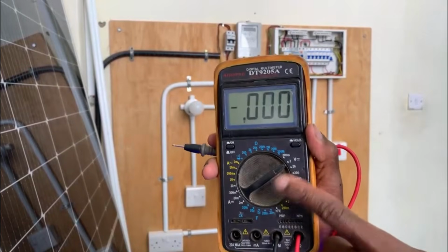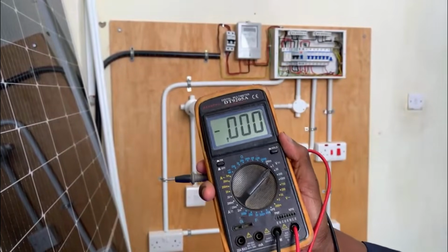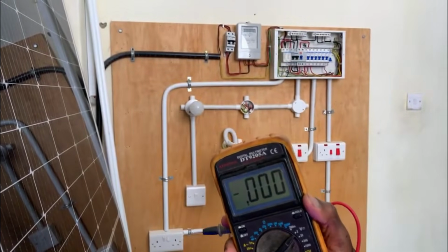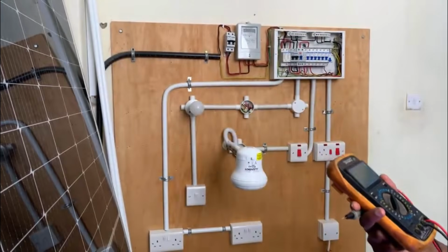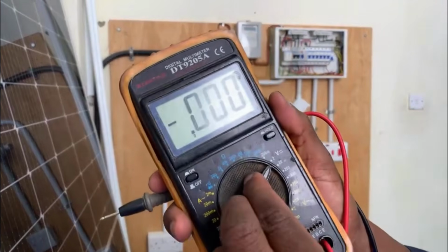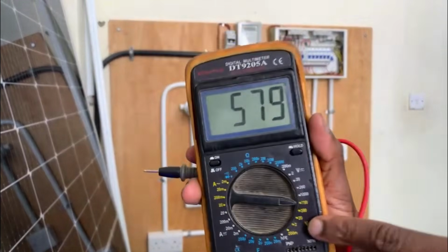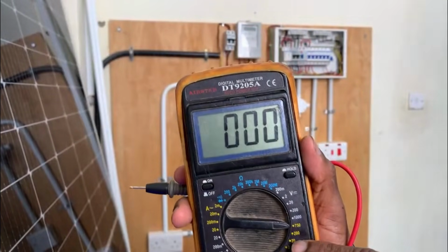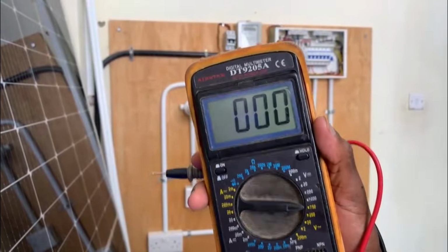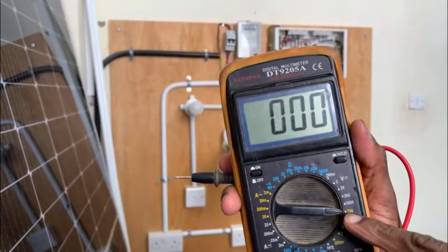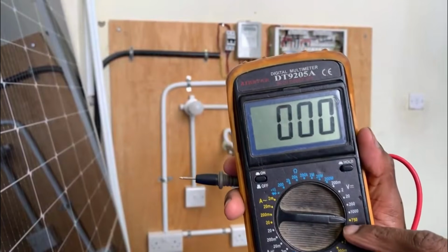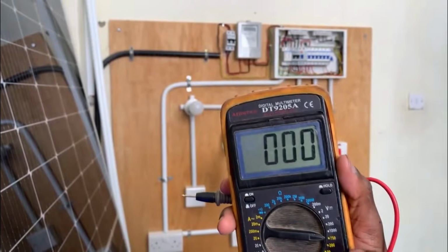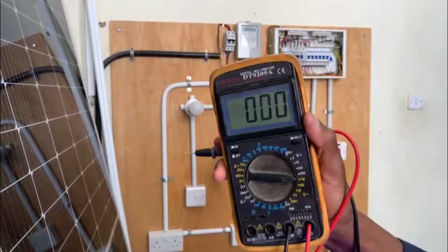So everything on this multimeter here is very intentional. It is not just placed there for the sake of it. So you must ensure that you understand correctly what you are recording. When it gets to AC, like our top boss had requested to record the readings, we also set it at 750 because we expect a reading of over 240. The closest setting to that is 200, and I would damage my digital multimeter, so I place it at 750. If I get anything between 200 and 749 volts, that is okay. My digital multimeter will not be damaged.